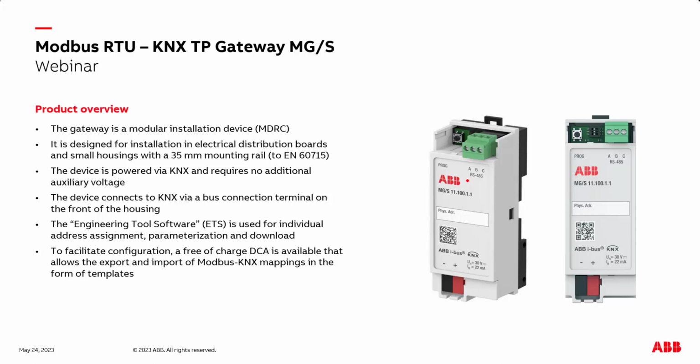The one and only tool to commission and download a KNX device is the ETS. So we need ETS 5 or ETS 6 for linking the group addresses, for parameterization, and so on. To facilitate the configuration, it is recommended to use the so-called device configuration app, DCA, which is free of charge.